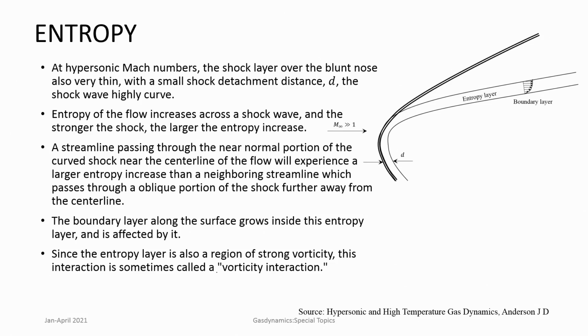The other characteristic is that generally the hypersonic vehicles have blunt shapes, their noses are made rounded, they are not at all sharp. As a consequence, the shock that develops around such bodies is a detached shock, a bow shock. Okay. We had discussed this kind of shock in the context of Crocco's theorem much earlier, where we said